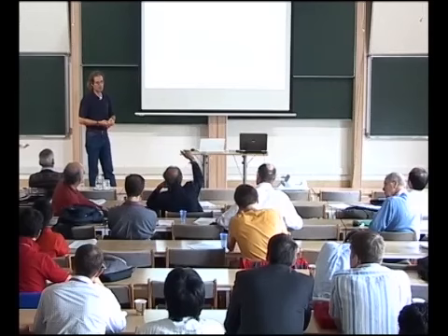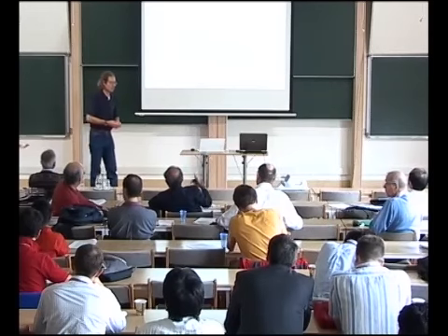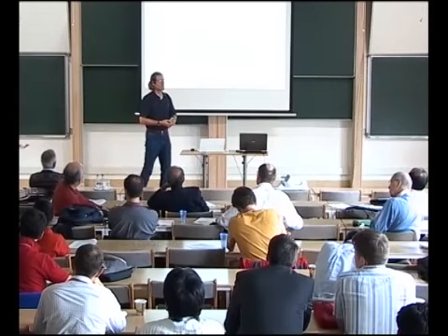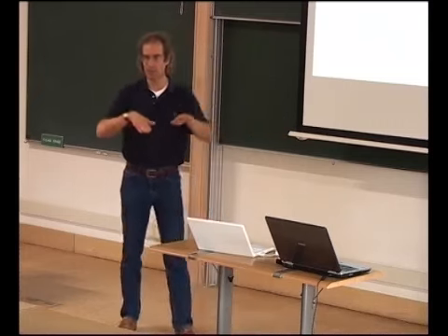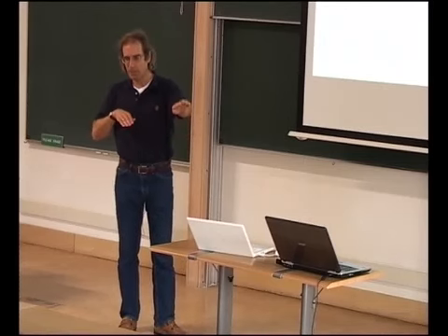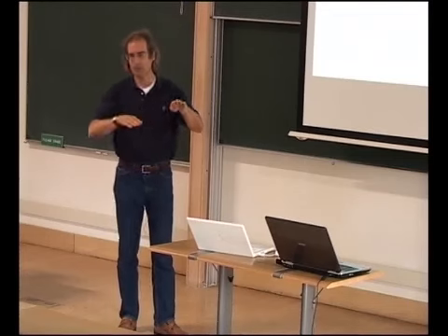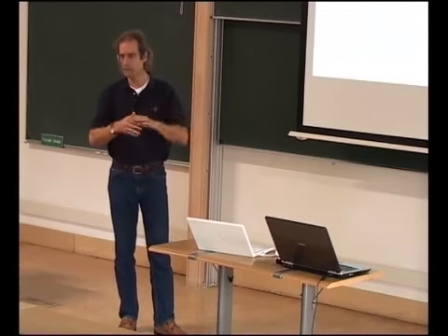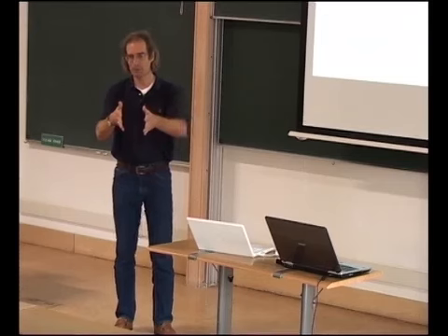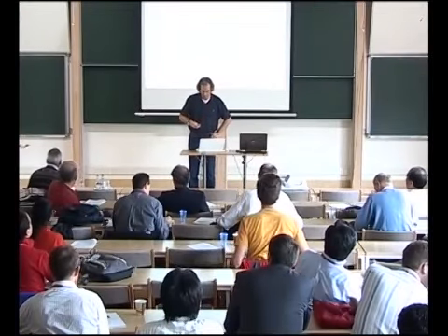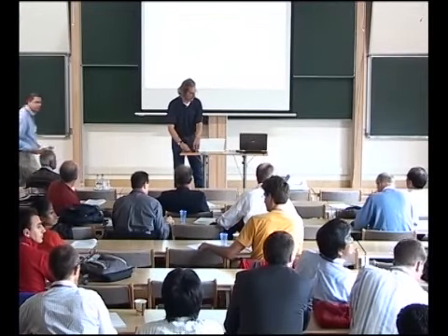One more quick question. On the mode 2 transitions you had, was breakdown always occurring earlier in one half of the width of the wave than in the other? It's a little bit complicated because there's a sinusoidal variation across the stream and it's not steady. The inlet disturbance has a low frequency. Yeah, that's what I wondered. So the breakdown will move from one side to the other. I showed you mostly the case where it's on this side, but if you wait later, it will be on the other side of the boundary layer.